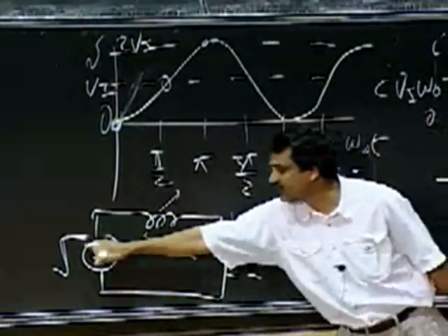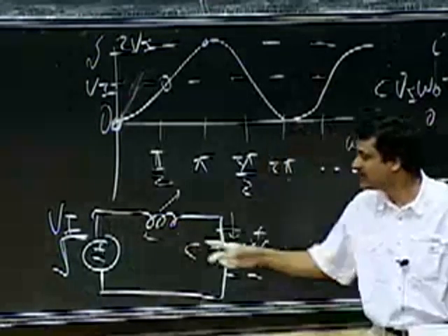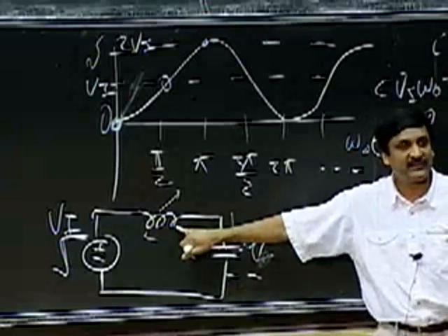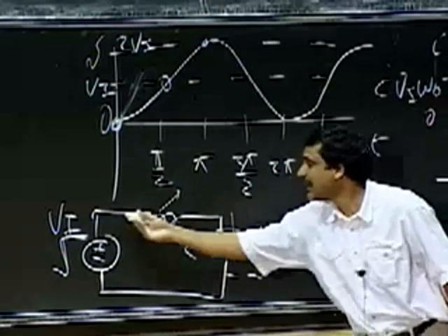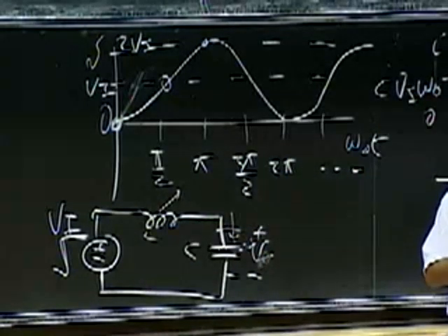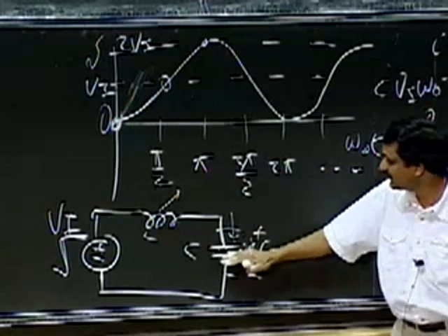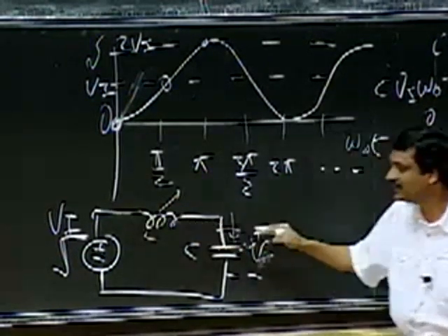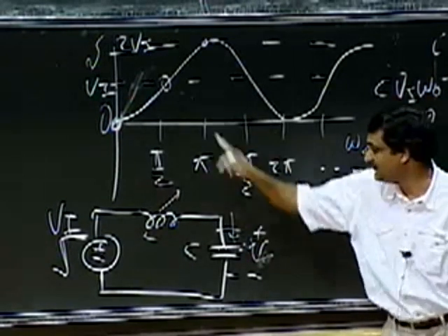But then VI equals this VI here. So when the two become VI, the inductor has 0 volts across it. Okay, so there's no longer a potential difference that's increasing the current in that direction. So at that point, at pi divided by 2, I have some current going through the inductor. But there's no longer a pressure forcing more current through the inductor, because this voltage reaches VI.